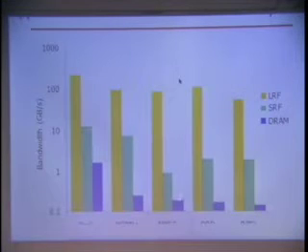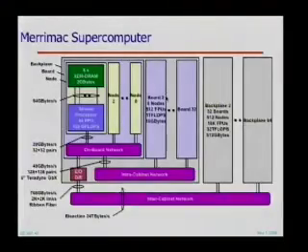What you can see is they're actually not stressing the memory a lot, which is good because that's the peak bandwidth of this sync DRAM. And as anybody knows, when they've used sync DRAMs, you don't get the peak bandwidth in anything but unit stride accesses. And they actually don't even stress, except for depth, the SRF bandwidth very much. Most of these are well down from that. But they're making most of their references by far from these local register files where the cost of the reference is small. And that's really where the efficiency of stream processing comes from, is making 95 to 98% of all of your data references from these register files sitting right next to the ALUs.